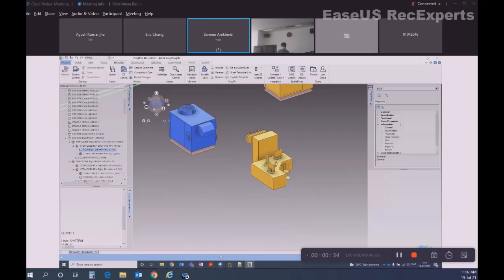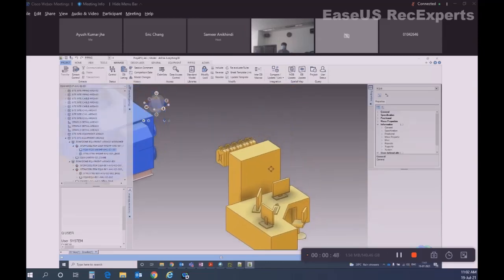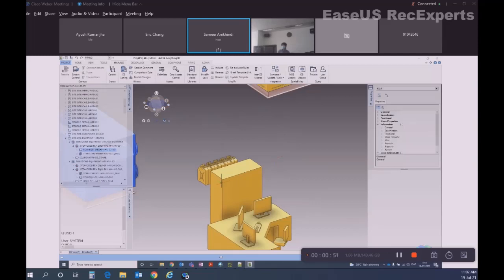So you know snap settings, snap activation and deactivation with the F3 key, dynamic hints. Let me talk about a few more things about this snapping and data entry in the coordinates. Let's go back to ID. ID command. See, if I have to enter data or if I am snapping, it will give the coordinate in the ID coordinates. It will automatically pick that coordinate.